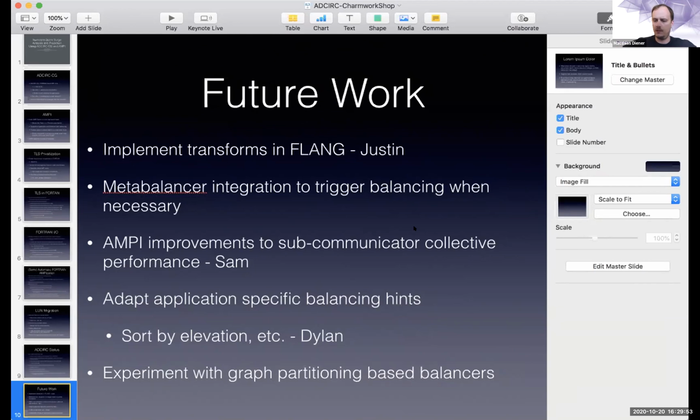I think Francois had a question here in the chat. About the images Joannes showed, what sets the spatial distribution of the grid nodes? Oh, so we go anywhere from about, in the operational meshes, from 30 meters, and then they extend out in the deep ocean to about 12.5 kilometers.